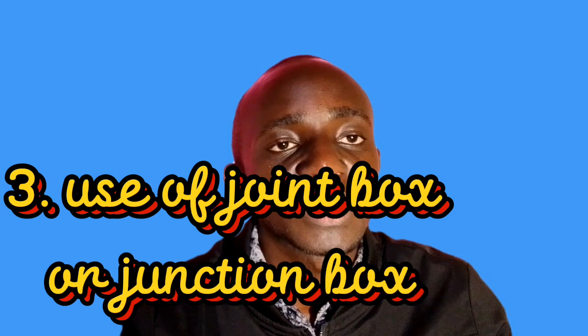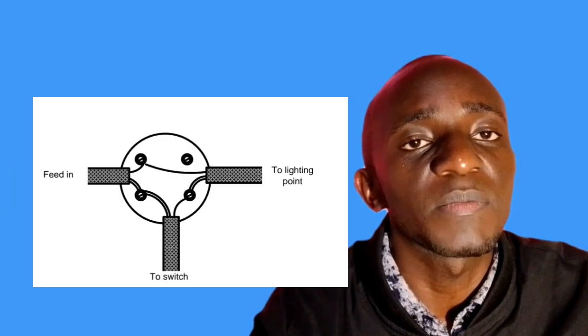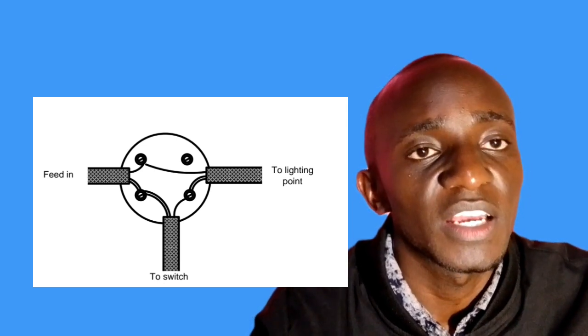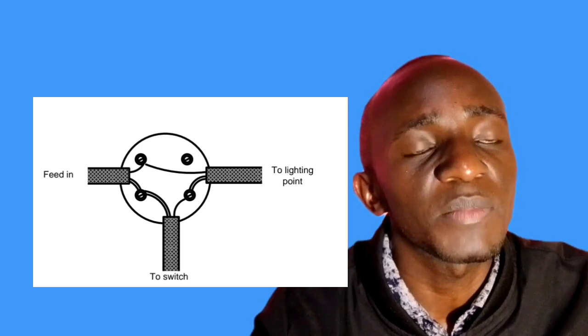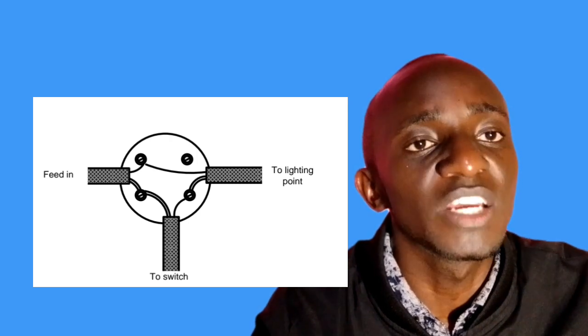The next method that we use in lighting circuit is by use of a joint box or a junction box. So this is how we do connection at the joint box. The cables from the supply, we know that supply comes with live, neutral, and earth to the joint box. So the neutral from the supply is joined to the neutral to the lamp, and the neutral which is supposed to supply the other lights or the other lamp. So we have those three connections.